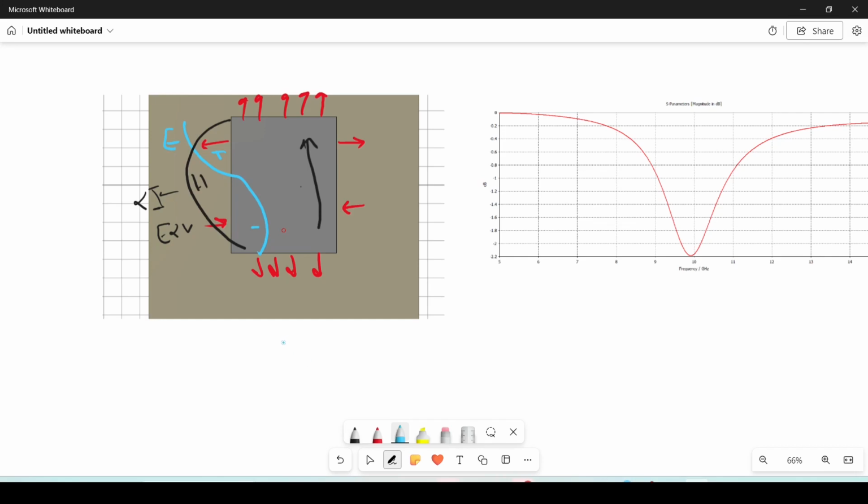So we can expect that if we look at the input impedance, Z input equals V over I, here V is minimum, like 0, right? So the input impedance is equal to 0, and on the opposite side, I equals 0, and then the input impedance equals infinity. It means that we have two values as we sweep from here to here. We can get from 0 to infinity.